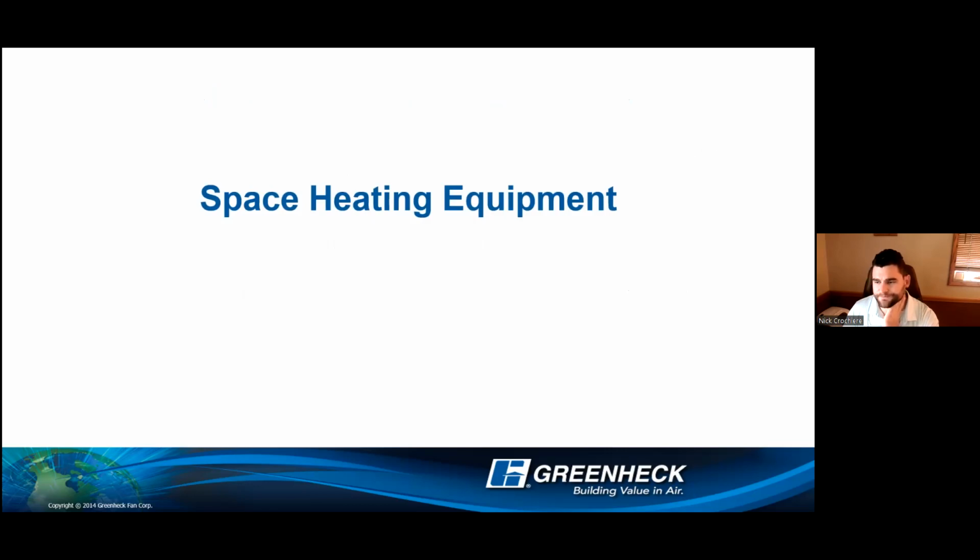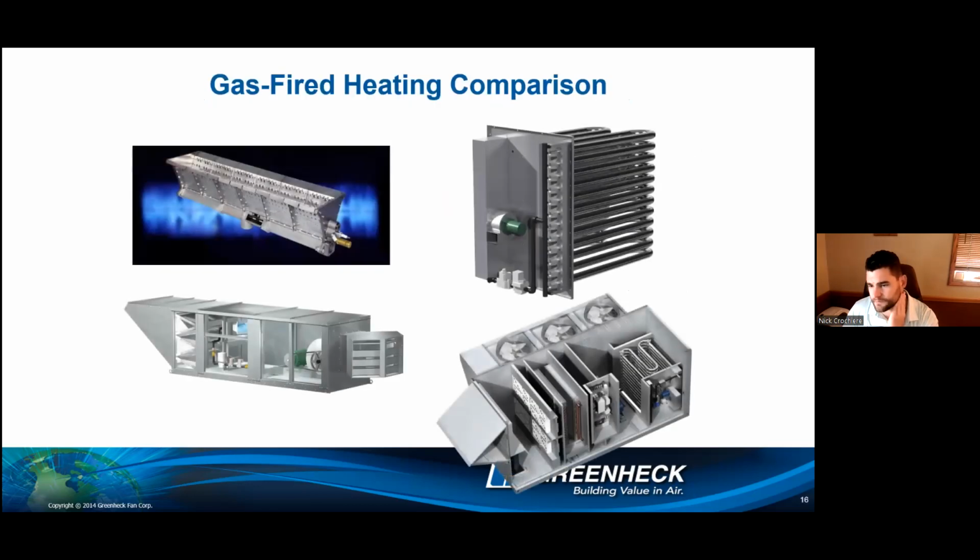Space heating equipment. So what do we see? Well, right here, direct fired comparison. Upper left-hand corner, you have our direct gas burner that is stainless steel construction with aluminum gas train. To the right of that is an IGX, or an indirect gas heater. So it's a furnace that we build and then put inside of a makeup air unit. Below that furnace, that is actually a DOAS unit, a dedicated outdoor air system. So that's looking at more comfort cooling, office spaces, things like that. We are seeing them pop up in a lot more markets now.